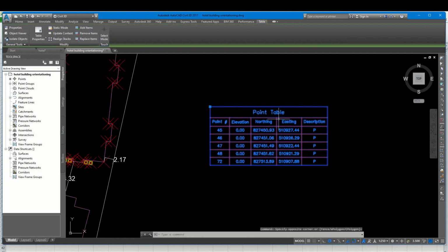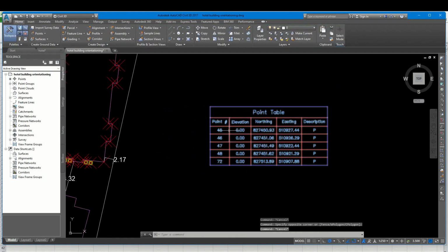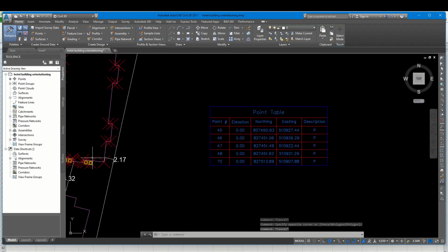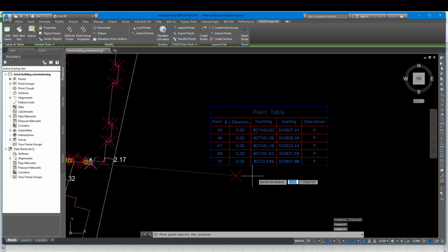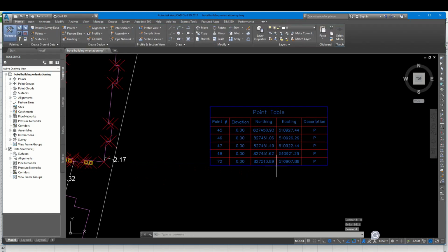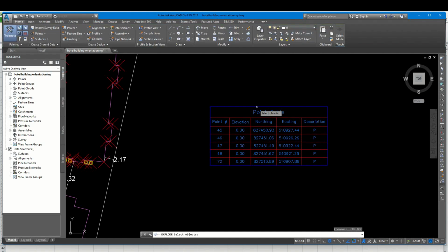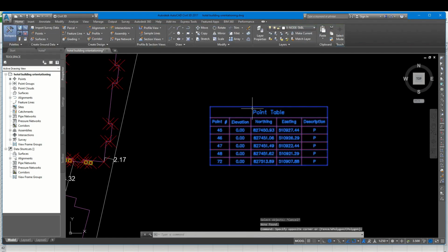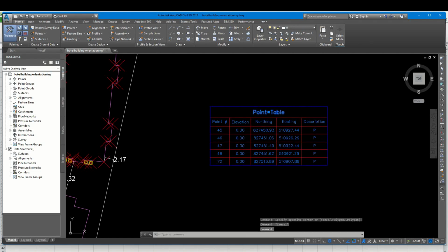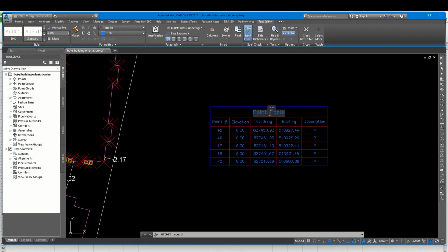Yeah. Why AutoCAD is so very wonderful is that if I should move this pillar point out, it will change. You see, I notice this pillar 45. It will change the coordinate position. So if I blast it, X to explode, that dynamic function has been removed from this condition. So I can just edit this and say points, pillars.